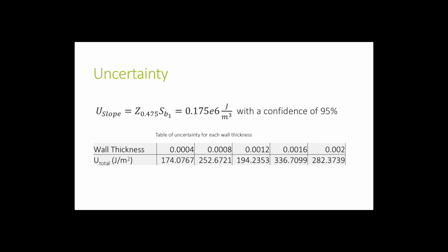To calculate the uncertainty of the measurements in this experiment, overall calibration is not available due to a lack of known standards in this particular situation. Instead, error propagation is relied upon. And because the sample sizes are small, the chi-squared approach to find the goodness of fit is not very accurate. But each sample set was visually plotted and confirmed to appear Gaussian.